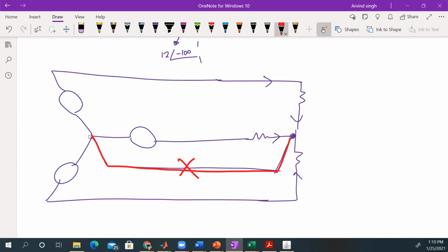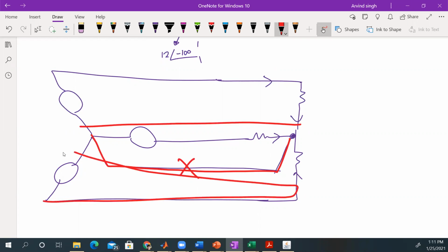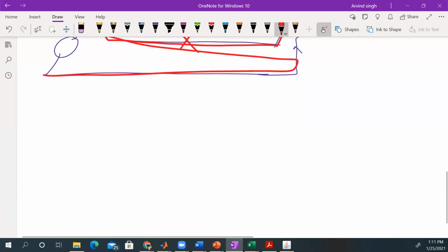So it saves money by simply not having a return. And it's not just one return. If we did it single phase, each one of these would have to have its own return, right? So we'd have 3 returns, and we don't want that, so it is as though you have a whole other circuit. You save half the conductor, basically, the whole return conductor coming back, right?